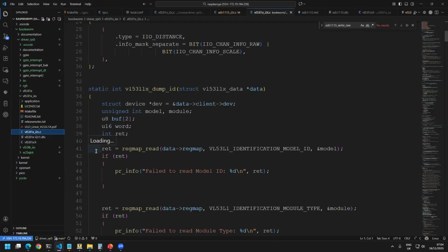So firmware is taking care of all of it, because there we cannot run Linux. We need a core C code, which is not even an RTOS, and which is based on a timer, because the speed of light is very, very high. So you have to calculate that very short duration of time, which can be done by the timer. So we are just measuring that time using the timer.